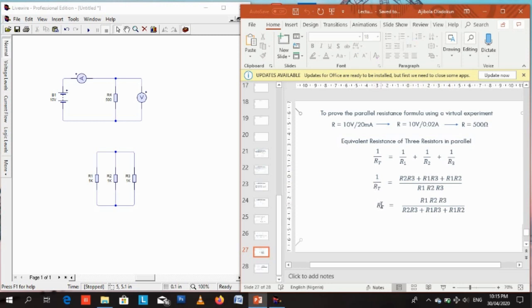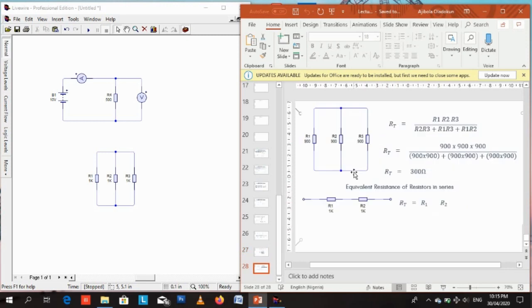So we need to flip the fraction on its head, flip it upside down, so R1, R2, R3 goes up, where the former numerator now becomes the new denominator, and the old denominator becomes the new numerator. I hope you understand what I mean by that. So now all three are connected in parallel.